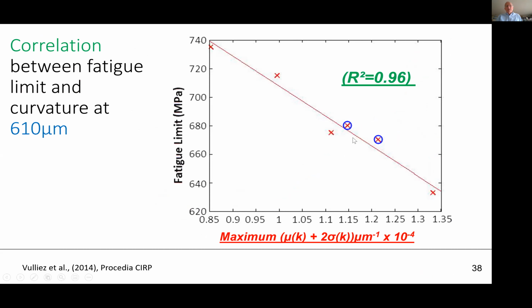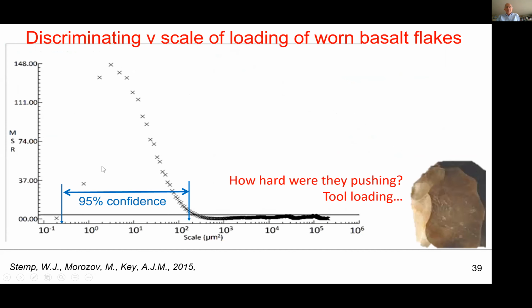One of the interesting things is that heat treated or not, these all fell on the same line. Maybe this would be true of smoother surfaces, but a big deal is made in the literature of residual stresses, and theoretically it's easy just to add in the residual stress and say, well, this changes the stress that the surface is actually seeing. For these surfaces, it didn't really matter, or didn't influence the R-squared. They all are on the line, and they're all behaving about the same.